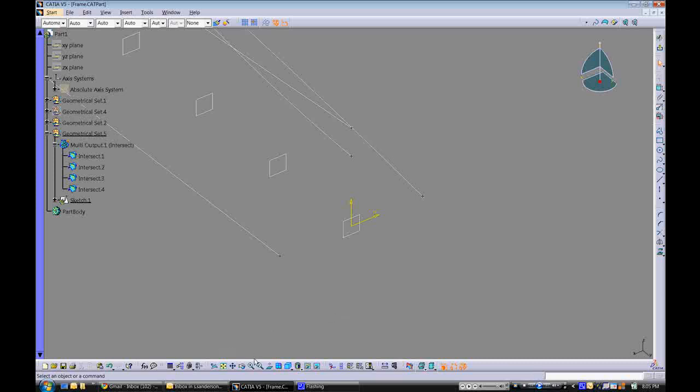And so the sketch is where you can actually define constraint-based two-dimensional drawings. So I just switched using the normal view button so that we're now looking orthographically at our sketch plane. That's an option that I've set so that you have to do that manually. By default, I think it does it for you automatically, which some people prefer.